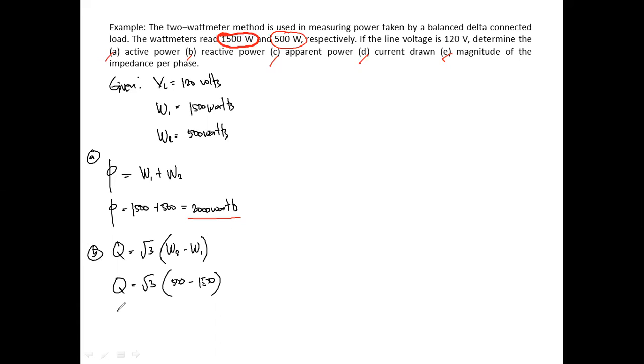This gives us Q equal to negative 1732 var. Since the reactive power is negative, this means that the load is capacitive.